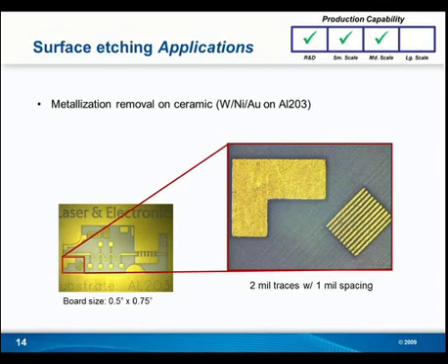Gotcha. Moving into another type of circuit creation and surface etching on UV lasers is when you're working with ceramic materials. Talk about that, Rory. Yeah, this is exciting for the UV laser because fired ceramics or alumina, Al2O3, come with a wide range of metallization. You can have tungsten, nickel, copper, nickel, gold, and the laser is able to remove all those metallizations with very fine precision, talking about the Gaussian beam, getting it focused very small, 15 to 20 micron, and then the straight sidewalls with the theta lens and the galvo scanner giving you vertical impact.